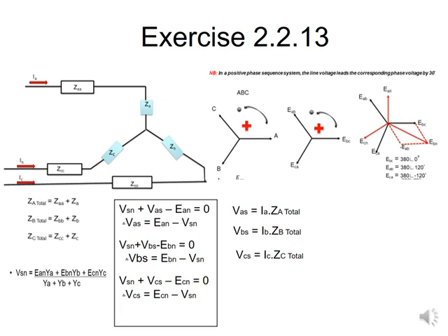And it should have actually triggered something for you, because unlike the tutorial you were given, they then said utilize the same type of network you've done now, where you're connecting your wattmeters to your A phase and your C phase. And you would have seen that your two powers did not balance out. So that is important. So even try this one that we did in class, but make sure that your power is balancing out when you are just doing your PA plus PB plus PC, compared to when you are utilizing your WA and your WC.